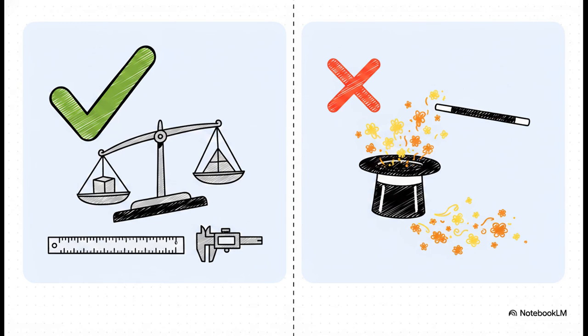Just look at the stark difference in terminology here. Safe engineering language sounds like reduced total phosphorus by X% based on measured values. High-risk dangerous language uses flashy terms like purified or eliminated. Claiming the water is completely purified creates a huge, legally dangerous misunderstanding of the actual science. It implies the phosphorus just vanished into thin air rather than being actively transferred to the solid phase. Always, always let your measured data do the talking.